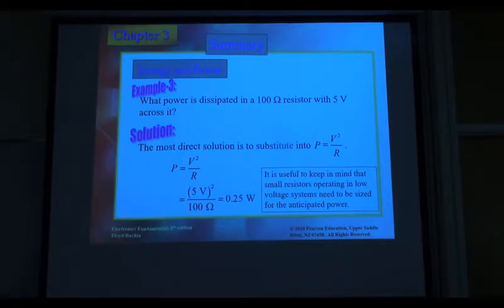It's very small. And the resistance equals 100 ohms, not that big. Usually it's something K ohm. This one is 0.1 K, so it's also very small. But the power, 0.25 watt, is not that small compared to others. So if we are not careful, we apply this 5 volts to this small resistor.